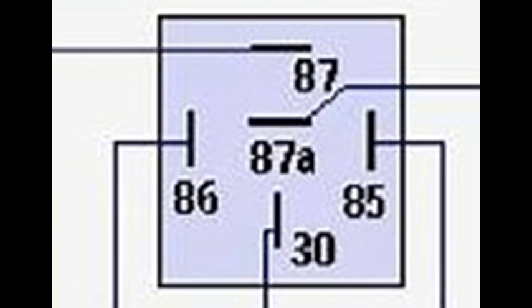It will have a 12-volt DC coil, and it will be a single pole, single throw, or single pole, double throw, that type of thing, with typically a 30 or 40 amp contact rating. So there's a standard to which these are configured. So you can see the terminals, and there's this diagram showing you a legend of the terminal identification.